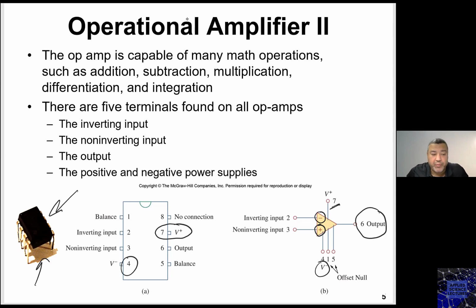So why do we have a positive, negative? We have a positive, negative power supply to the operation amplifier because we may expect our signal to vary between a positive and a negative range, right? So in order to reproduce the signal, it makes sense that my operation amplifier also operates with a positive negative.